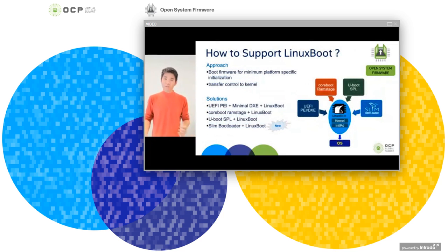So how can we support LinuxBoot? Well, Linux provides very powerful capabilities. The Linux kernel still lacks knowledge of the platform, such as the memory controller and also the UPI interface. So the solution is very simple. We still let the firmware do the very minimum platform-specific initialization and then transfer control to the kernel space as soon as possible.